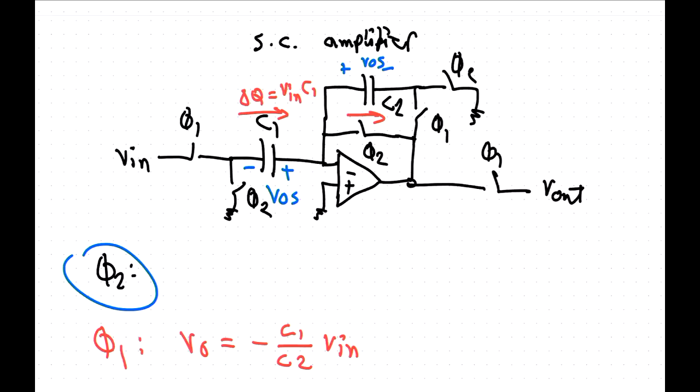The other thing is that the intrinsic gain of transistors is much smaller in really short-length technologies, and that means there's stuff you can't do. Normally the way people get around it is that they use some old-fashioned, high-voltage transistors.